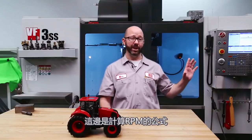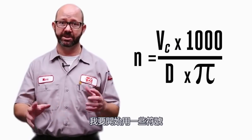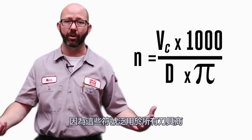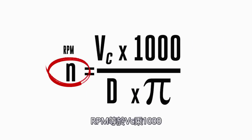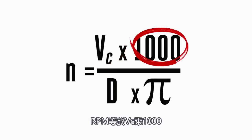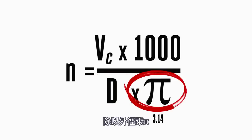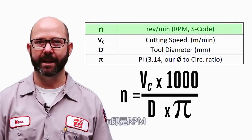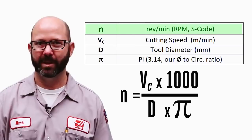Here is our formula to calculate our RPM. Now, I'm going to start using some symbols, some notation, because those are the symbols being used by all of the tool suppliers now, and you'll need to recognize them. RPM equals cutting speed times 1,000, all divided by our diameter times pi. N is our RPM, revolutions per minute. That's the S code in our program, what we're trying to solve for.